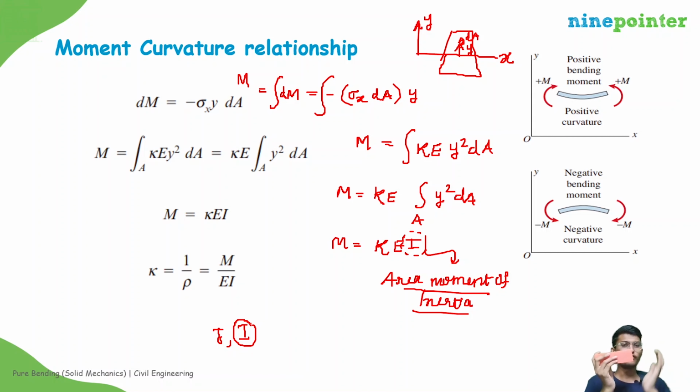Similarly, if you are bending like this, what is the vector representation of this moment? From the right hand thumb rule, we get it in this direction. It will be towards you; it shows reversed in the camera. So the axis is like this for this bending moment, and the I which you calculate should be about this axis.